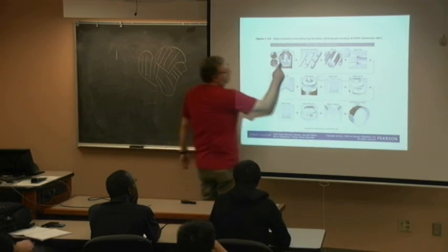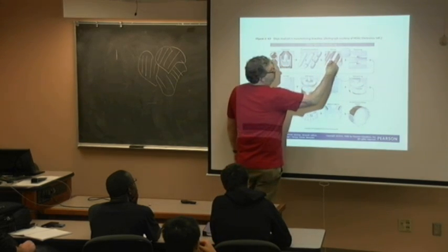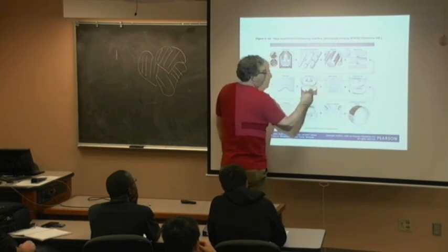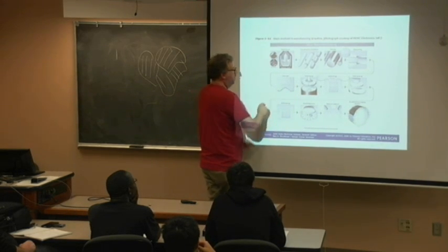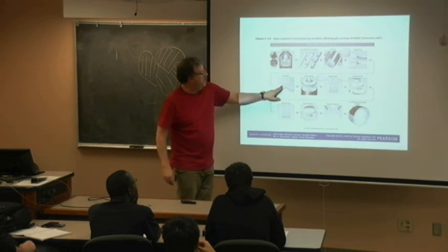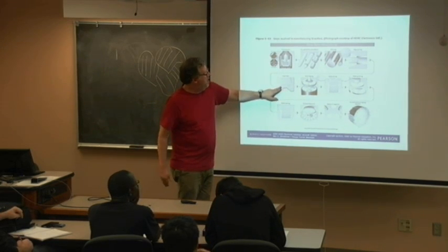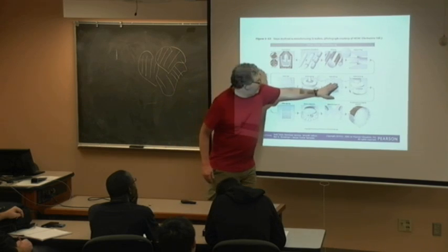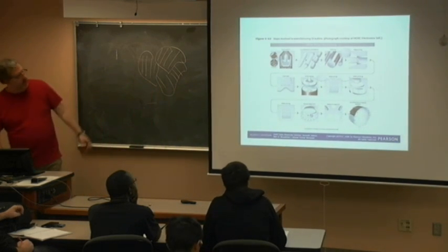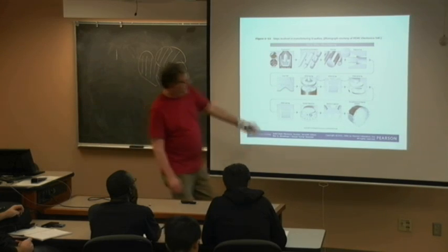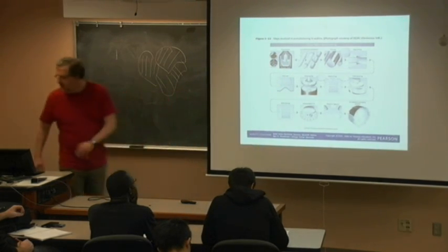You take the boule, you cut off the ends, maybe you recycle them. You do the wire sawing, and then you do the polishing. Laser, each wafer in an Intel process is going to have a serial number on there, so you know its whole process flow. You polish it and everything, and you end up with the wafer cassette. And then these are flying around in those little modules you saw in the clean room. Looks like the Star Wars capital city.